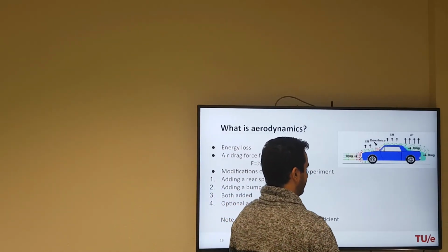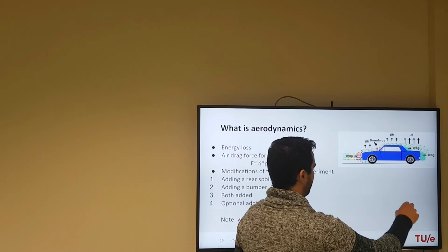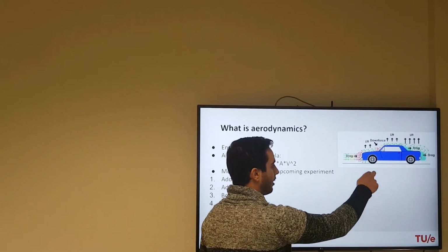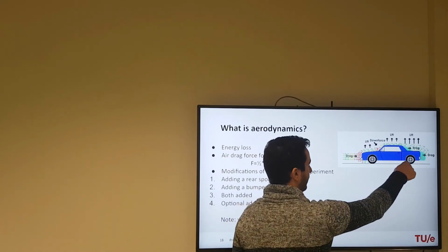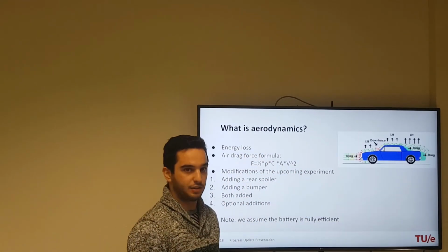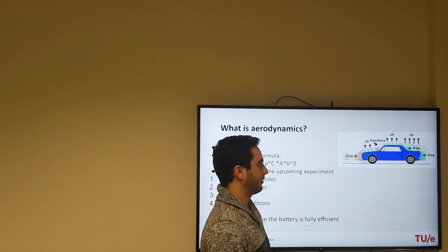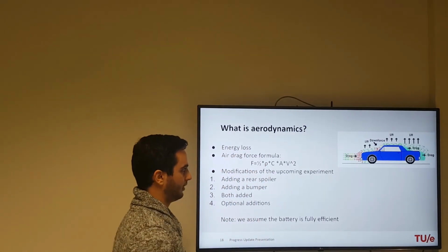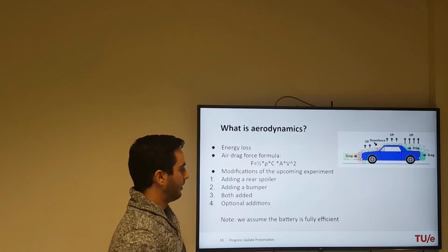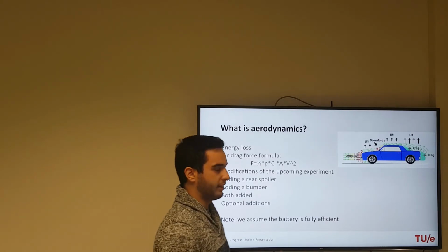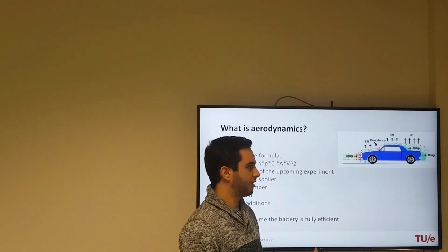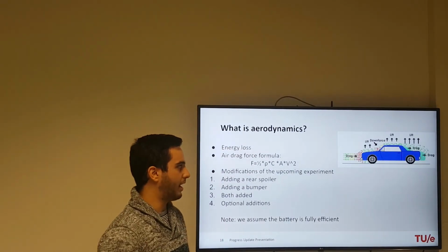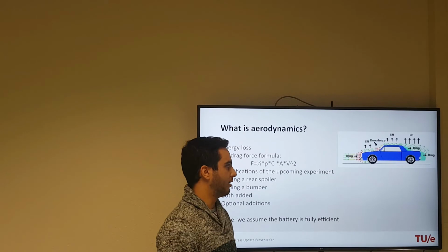The bumper helps the aerodynamic characteristic of the car by not allowing airflow under the car. Owing to this, the air drag coefficient might go lower, and we're going to create a downforce, which is going to increase the grip of the car and give higher stability going through corners.